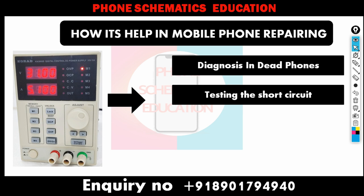For example, if there is a high current draw without pressing the power on/off button, when you connect your DC supply to the motherboard and it takes current on its own, I mean an automatic reading, without pressing the on/off button, that means there is a short circuit.